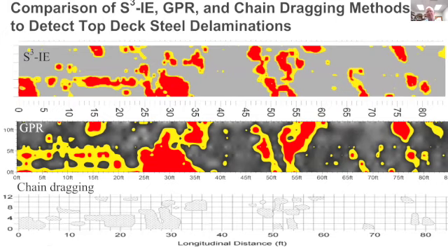So here's a comparison of the sonic surface scanner, the S-Cube with impact echo, at the top, to ground penetrating radar that we did. This was analyzed based on attenuation of signal and normalizing for depth of rebar. And the chain dragging at the bottom. These GPR results were calibrated against the impact echo because you have to decide thresholds of corrosion in rating this. Areas which are showing more attenuation of your GPR electromagnetic wave signals. But you can see reasonable correlation of all the methods.